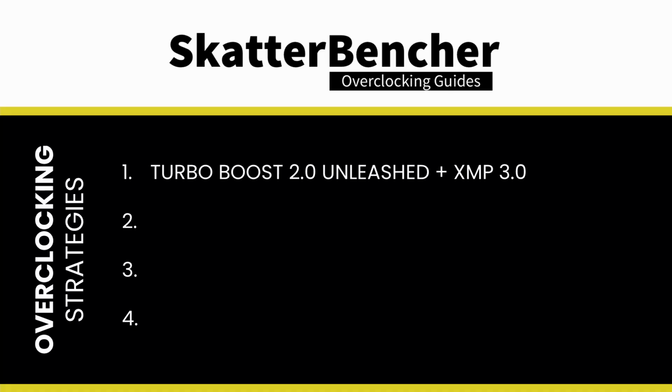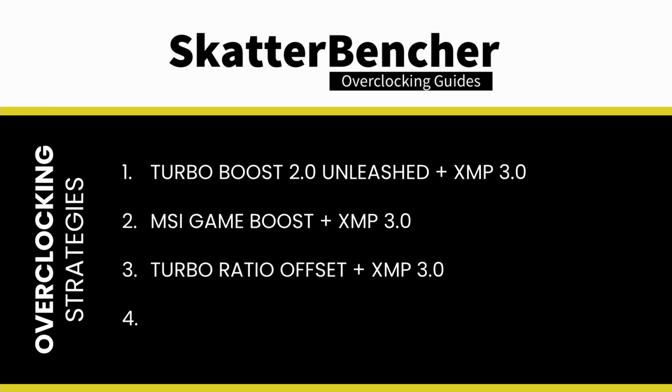In this video, we will cover 4 different overclocking strategies. First, we increase the performance headroom by unleashing the Turbo Boost 2.0 limits and enabling XMP 3.0. Second, we test out MSI's Game Boost one-click overclocking button. Thirdly, we use MSI's turbo ratio offset feature to further increase the performance. Lastly, we do manual overclocking to get the most performance out of our system. However, before we jump into the overclocking, let's first have a look at the hardware and the benchmarks that we'll be using in this guide.